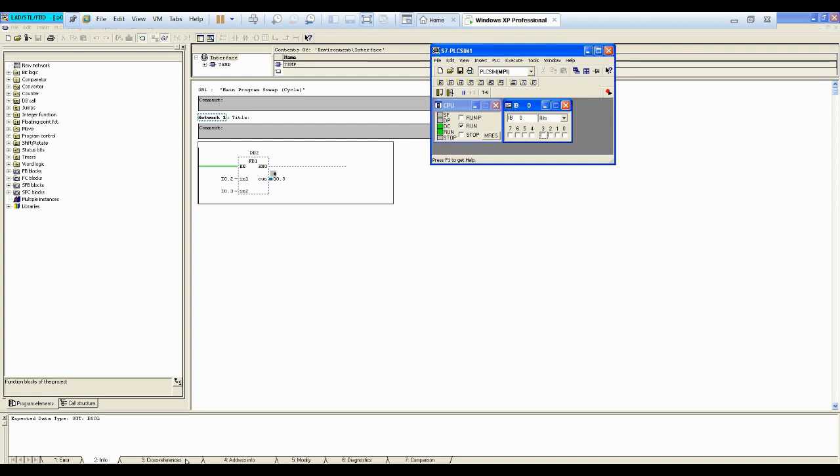We have multiple areas, multiple processes, multiple machines running in there, multiple control loops to be executed. So based on our need, we have to select FBs. We will create FBs for motors, valves, and for certain applications like boilers. So we will make different control loops in FBs and FCs to make our program very clear.